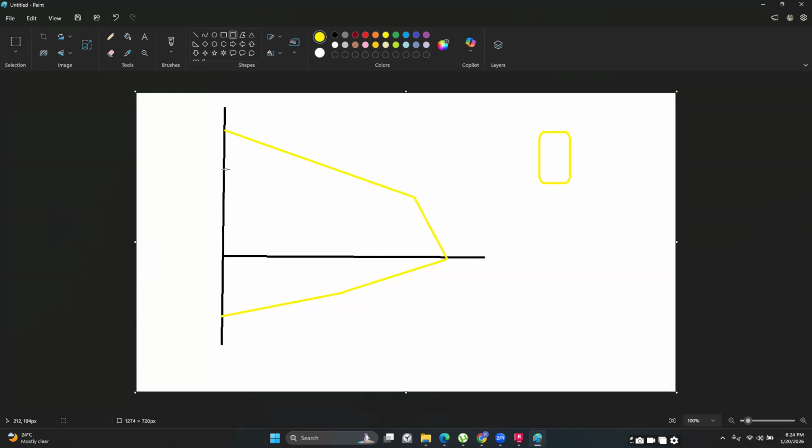All right. So when you have, say, your axial forces in this direction and your moments in this direction, you know how to read a graph. So along the x, you have your moments. So here, say you have your moment. If you are to read this, you would have M here and the axial load here, P. So any combination that is within this failure envelope or this graph here, it is safe. But if anything appears outside here, it is unsafe.